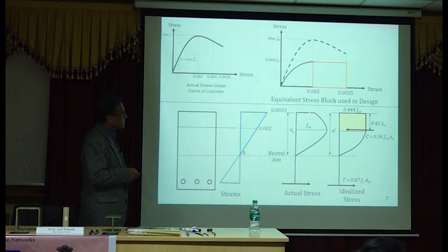So this is the actual parabolic stress strain diagram, and the idealized stress strain diagram is this for IS 456. All that they have done is they found the total area under the curve of these two blocks, and they tell you that's 0.36 fck xu, where xu is the depth to the neutral axis from here to here, and then the maximum stress is 0.444 fck.